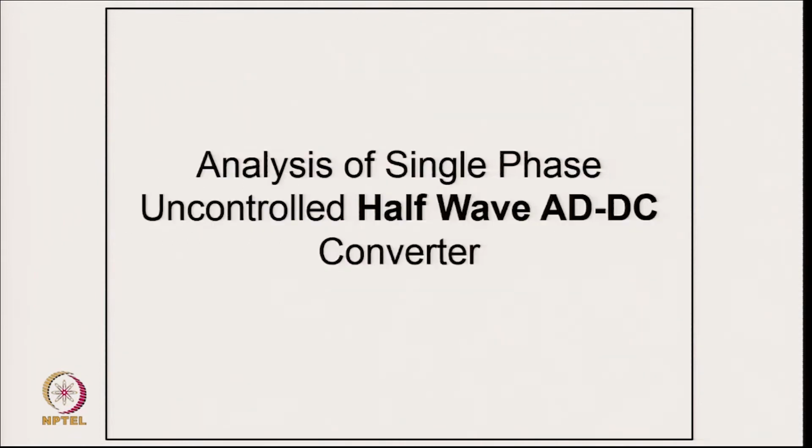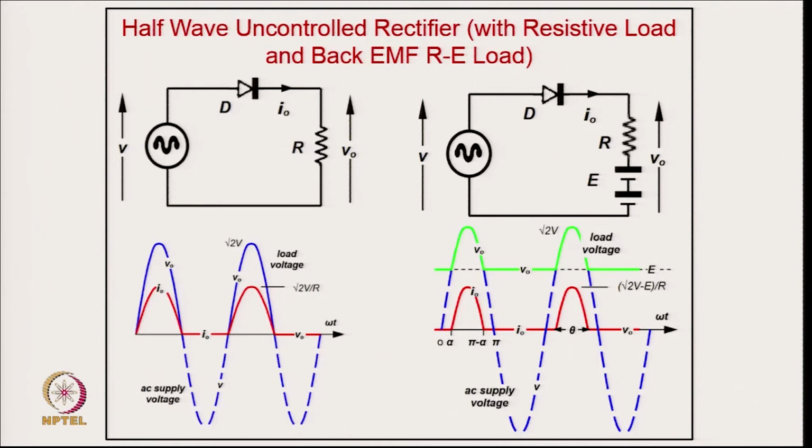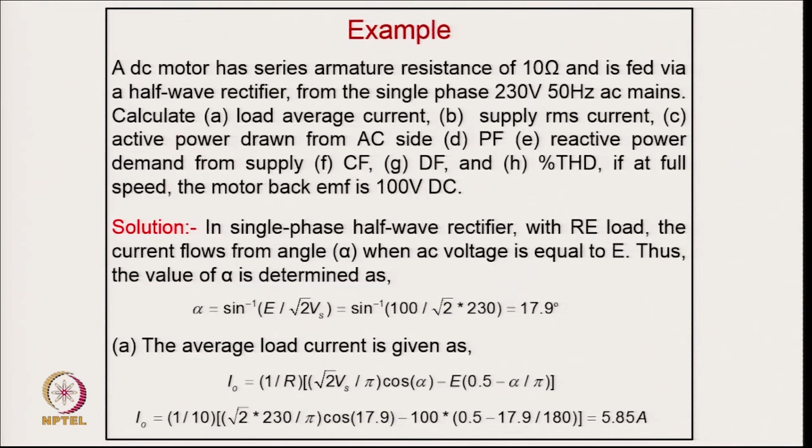Coming to the half wave rectifier, you get current only in the positive half cycle, where the voltage is positive, and you can see that you are also injecting a DC component into the supply system. Because of this, it is used only for very low power battery charging. You are not only injecting harmonics but virtually even the DC component into the supply system, which may even saturate the transformer of the supply system.